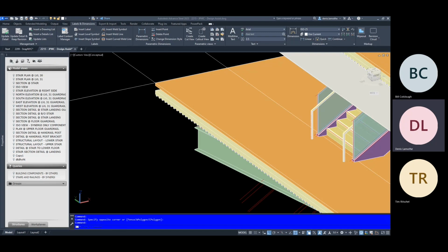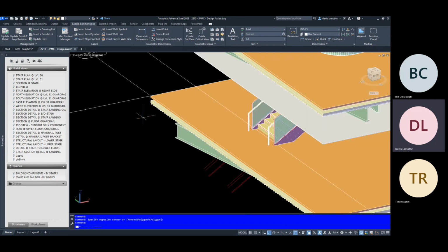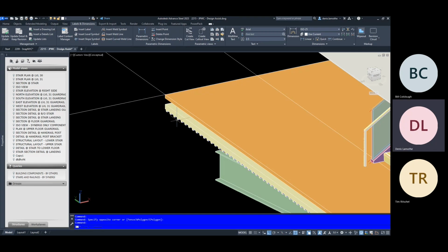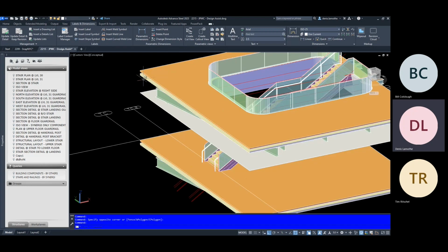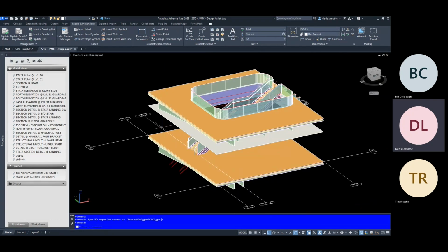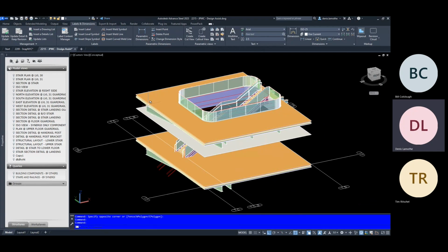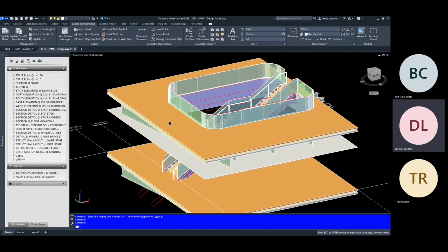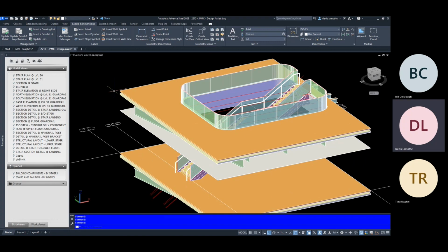Okay. But when it comes to modeling in Advanced Steel, unfortunately, since it's built on the AutoCAD platform, the dimensional constraints that I was talking about only work in 2D. They don't work in 3D. They won't move or modify any solid components or modeled parts that you have. So unfortunately, unlike SolidWorks or Inventor, dimensional constraints can't really be used for modeling, to my knowledge. I haven't seen or heard anyone be able to incorporate that. So yeah, it's a regrettable feature. It'd be nice to have.